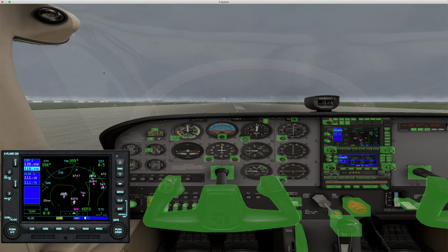I didn't talk much about these needles here. These are your ILS needles. This horizontal line, on the approach, should be in line with this dotted line. If it's high like this, it means you're a little low, and then the vertical needle shows your lateral positioning relative to the airport. So ideally, as you're coming down the glide slope, these would be a perfect crosshair, and that would tell you that you're in perfect alignment.